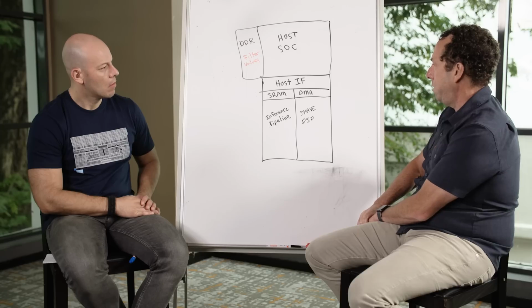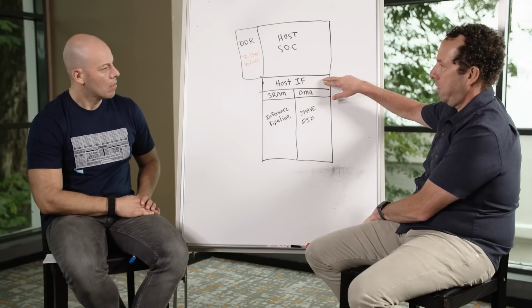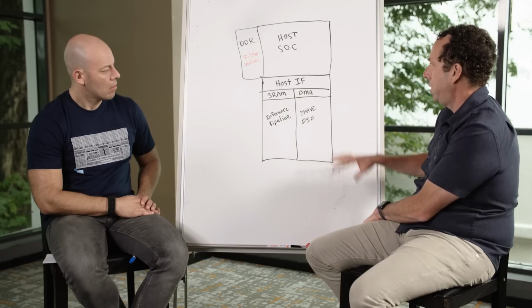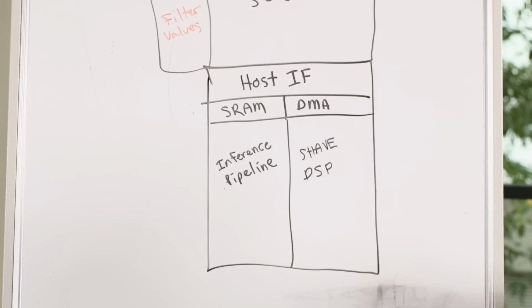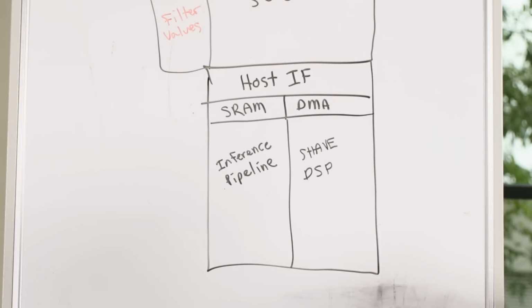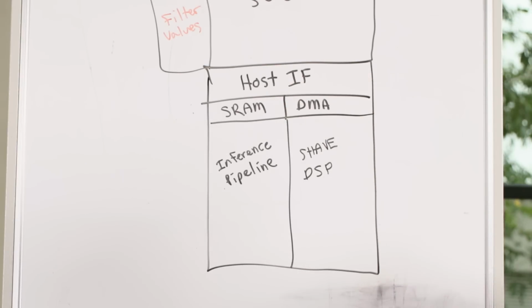So we basically have two components. One is the host interface and the control for the NPU, and then the rest is the compute portion. The host interface portion communicates with the host that does all the scheduling and memory management. The host interface also controls the scheduling on the device, power management, those kinds of things. And then everything below here is compute.